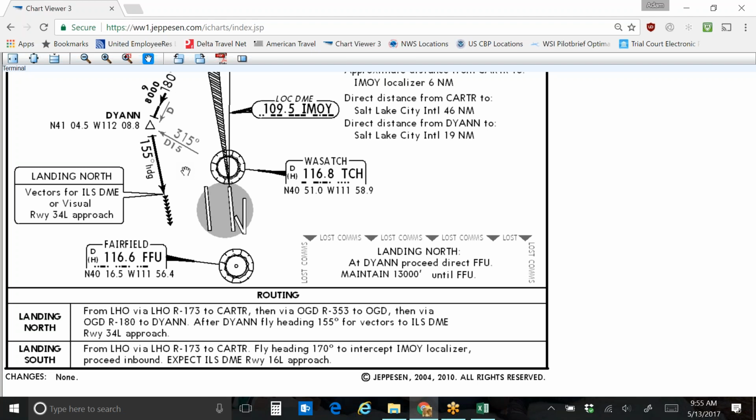And then our system kept going off. First it says traffic, and it's just a caution message. It's not telling you to do anything. But if it gets to the point where the computer thinks that traffic is dangerously close to you, the TCAS system will actually give you verbal instructions as well. So it got to the point where it gave us what's called a TCAS advisory message, and it basically says traffic, turn right or whatever. It'll tell you right on the display what direction it wants you to go.